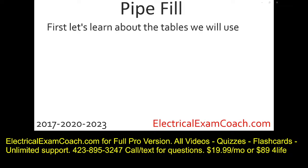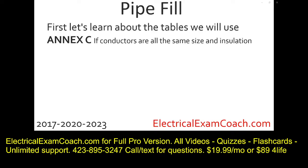Let's go ahead and learn about the table that we'll use if they are all of the same size. We're going to use Annex C. If you've tabbed your code book, you have an Annex C tab, and if you haven't tabbed it, you can just follow along. If the conductors are all of the same size and insulation type, we get to use a cheat sheet in Annex C. It's one of my favorite tables in the code book.